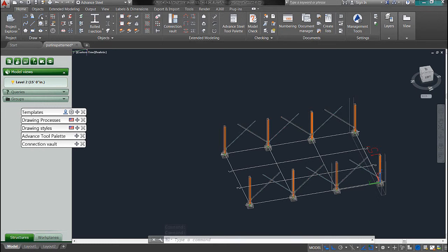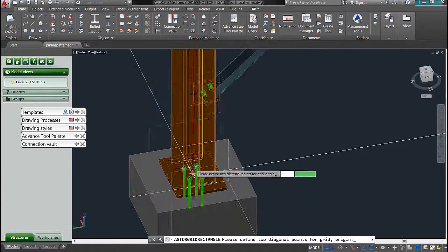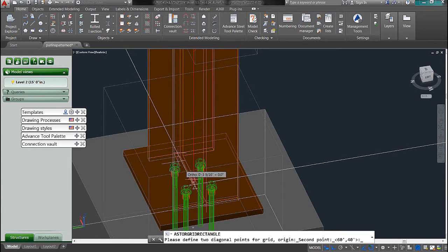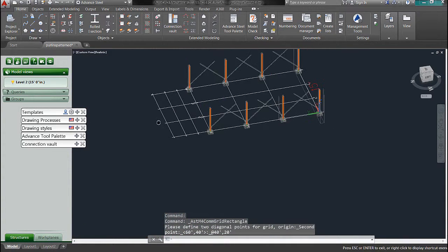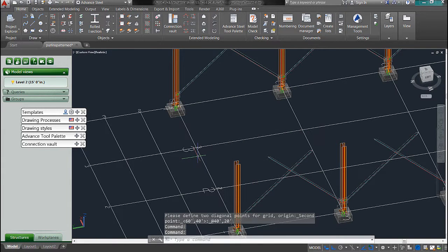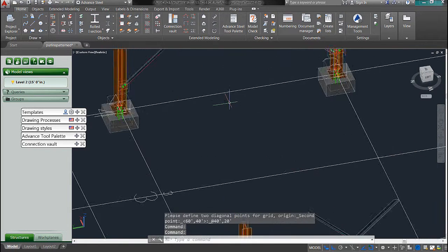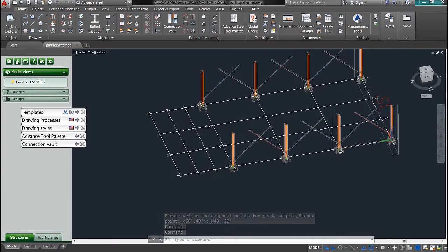And I'll go ahead and create myself a building grid just to help lay this stuff out, because I am going to 40 feet by 20 feet. I am going to add some columns and beams in here. So there's my building grid. Now I want to add some beams, which will be around the perimeter of the mezzanine.